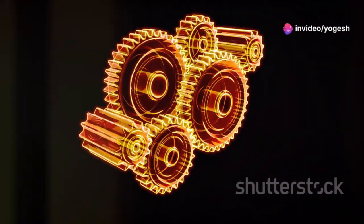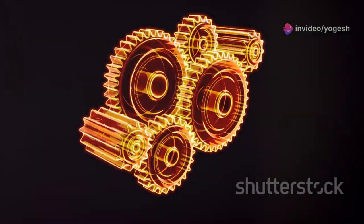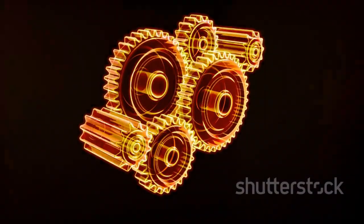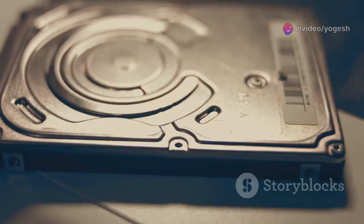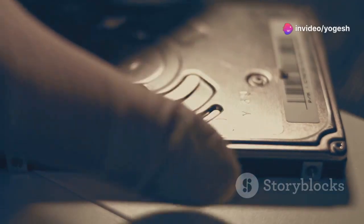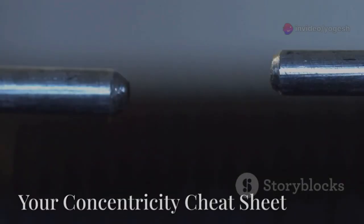The key difference: concentricity controls the median axis, while position tolerance controls the feature's axis. For most real-world applications, position tolerance is sufficient and far easier to verify. That's why you'll see position tolerance used for coaxiality much more often than concentricity.